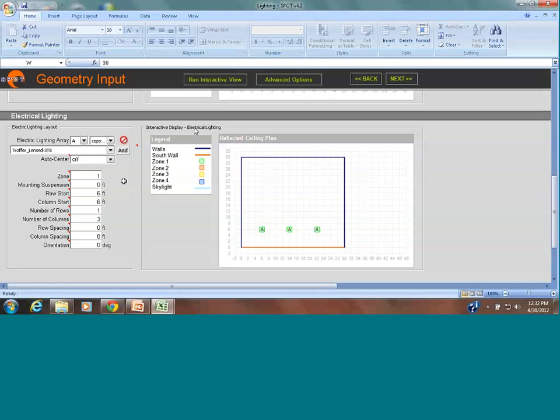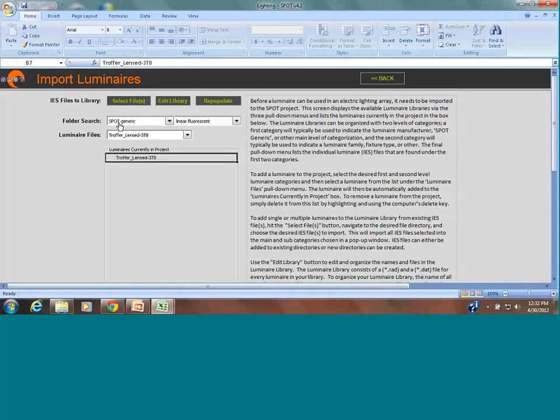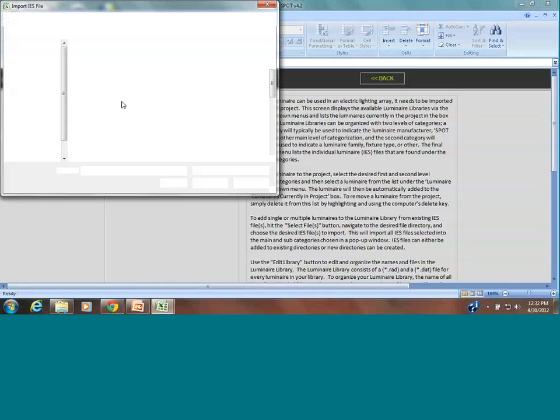This is where you need to have coordination with your electrical designer. Let's say they have selected a light fixture suitable for this classroom. So how do you bring that particular light fixture in? The way we do that is to go back to Add again, and you notice here IES. IES stands for Illuminating Engineering Society. IES files to library. So I can select a file.